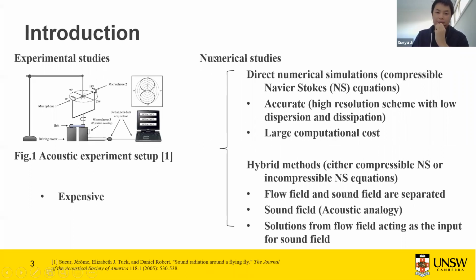The other option is numerical studies. As for numerical studies, we have two types of numerical solution. The first is direct numerical simulation. It is based on the compressible Navier-Stokes equations, because sound is a byproduct of compressibility. It is very accurate because typically we use high resolution schemes with low dispersion and dissipation. But the computational cost is very large, especially for the 3D case, because we need to set the buffer zone to prevent the reflection of the sound,